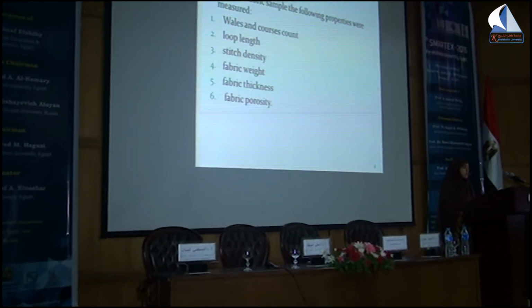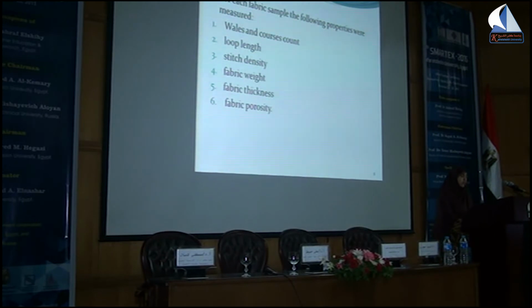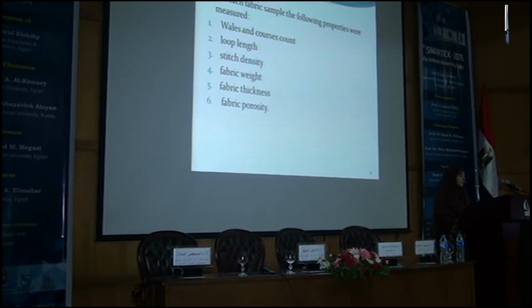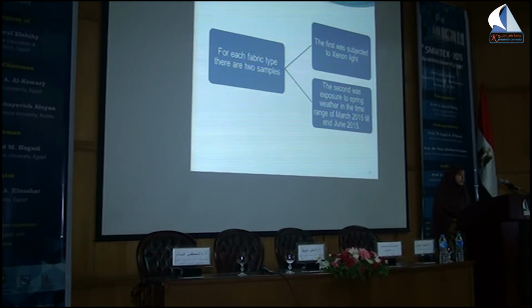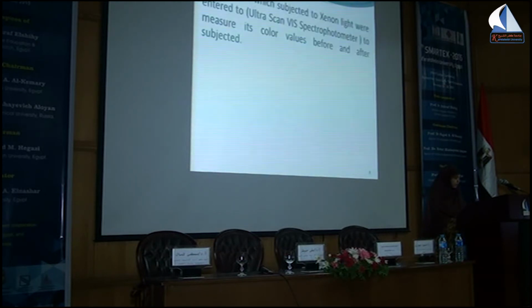The properties measured for the fabric samples were wales and course count, loop length, stitch density, fabric weight, fabric thickness, and fabric porosity. For each fabric type, there are two samples. The first was subjected to xenon light, and the second was exposed to spring weather in the time range from March 2019 till June 2019.